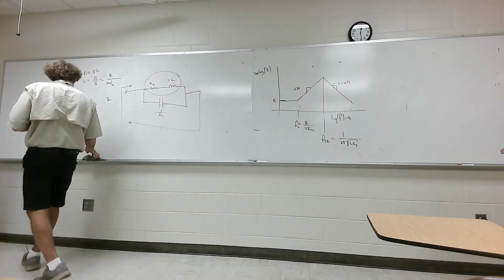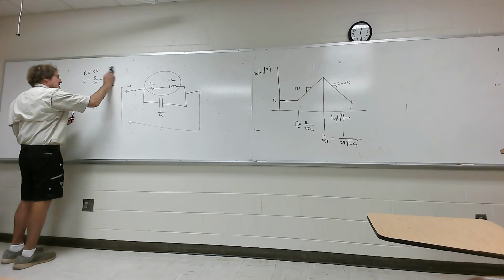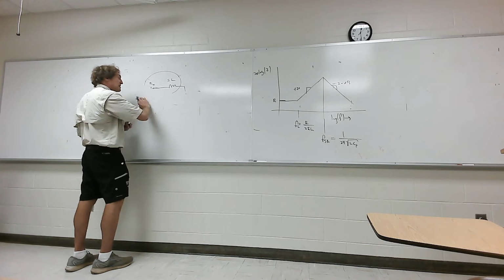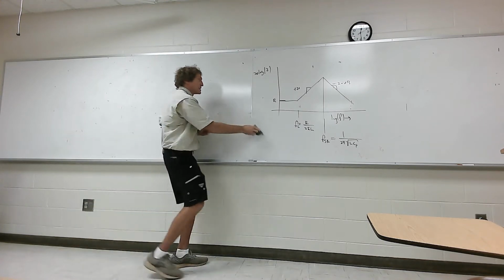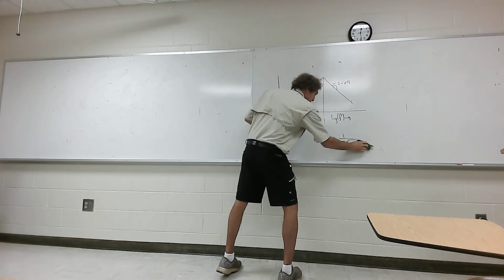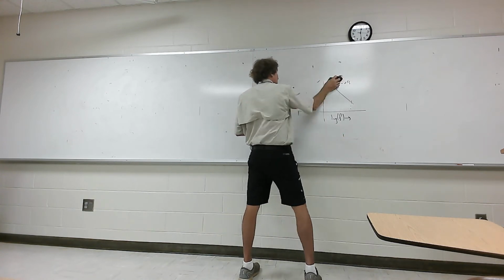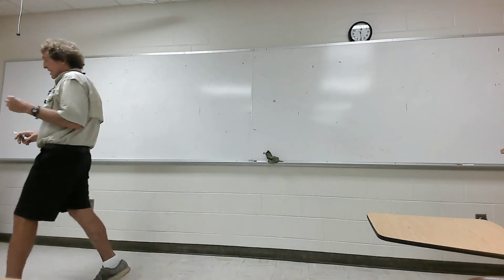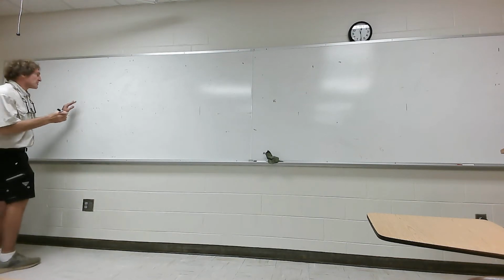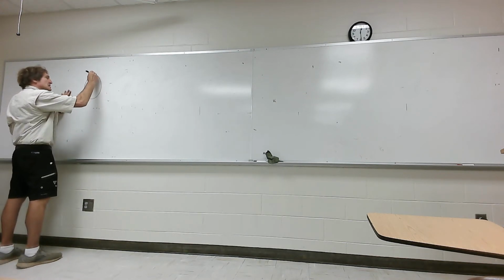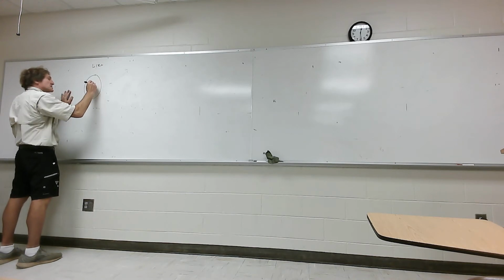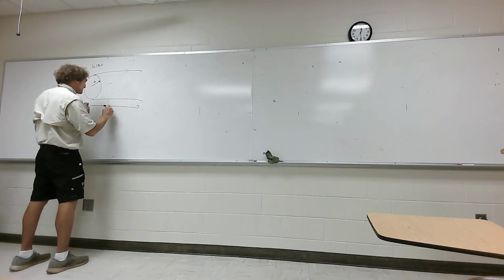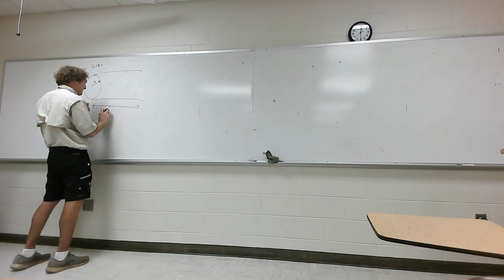After that, the next thing we have to talk about is wires and what they look like at high frequencies. And we've already talked about skin depth, right? Yes. All right, so now what we do is talk about what the wire's AC and DC resistance look like, and then in inductors, AC and DC internal inductance. So the first thing is when we have a wire, this is just a wire, it's going to have a given radius A, it's going to have some length L, and maybe I should use small l here.